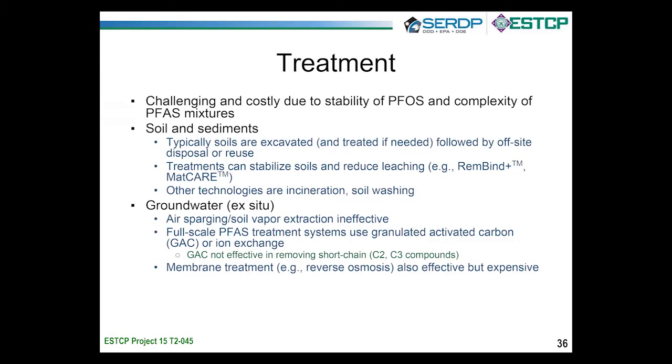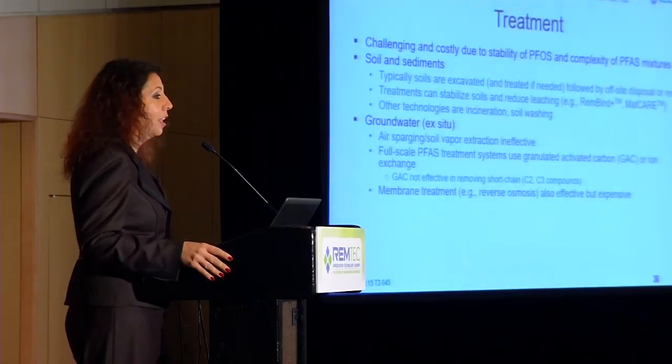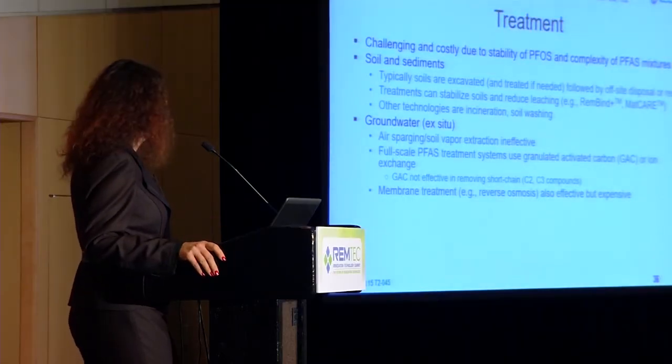So that's one challenge. The other challenge for treatment is the complexity of the PFAS mixtures that both Jennifer and Chris alluded to. In terms of what's available at our disposal as far as treatment methods for soils, we typically excavate soils and treat them if needed, followed by offsite disposal. There are a number of products out there to stabilize the soils and reduce leaching of the PFAS compounds. There's a couple of products out of Australia that are being demonstrated all over the world. And then other technologies include incineration and soil washing.